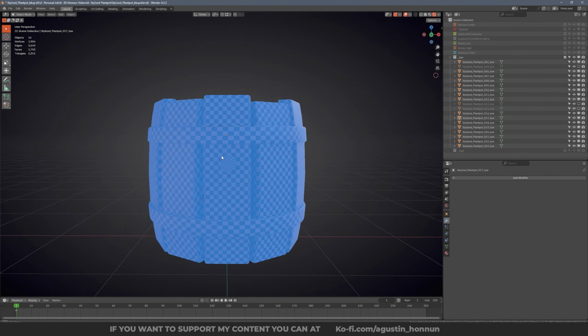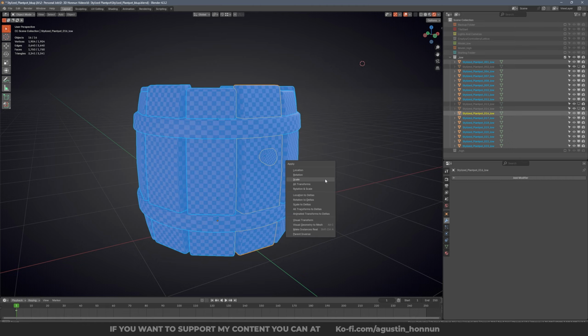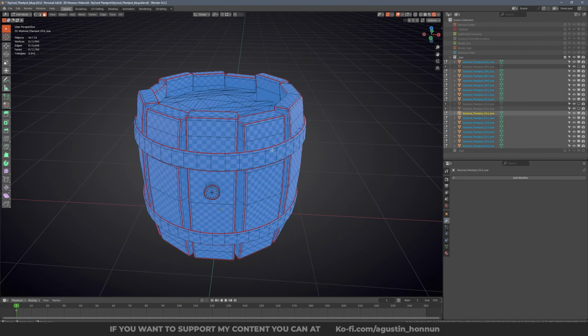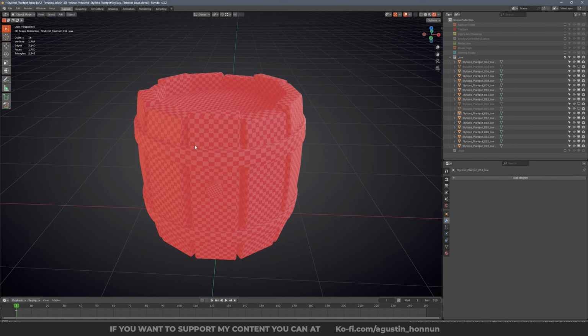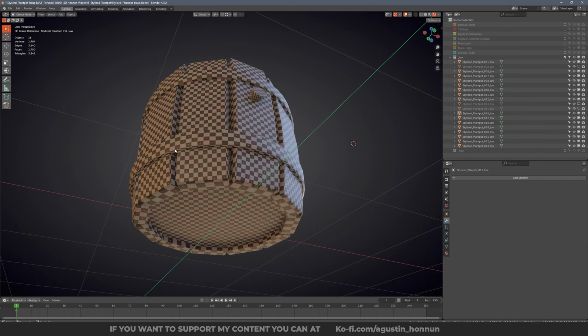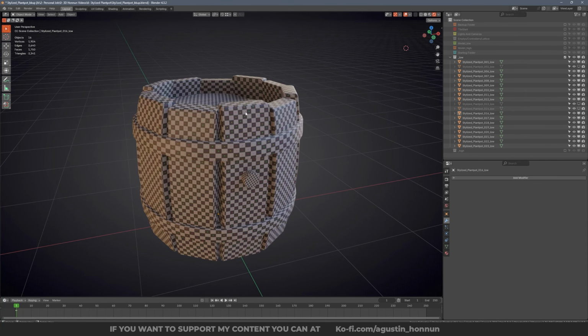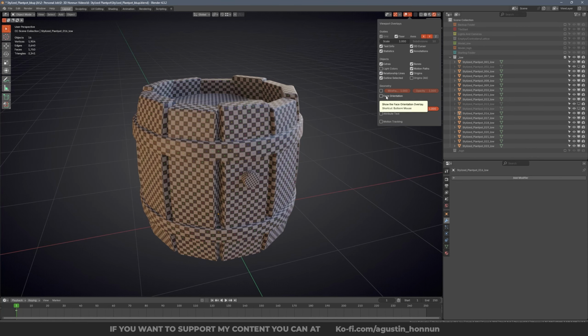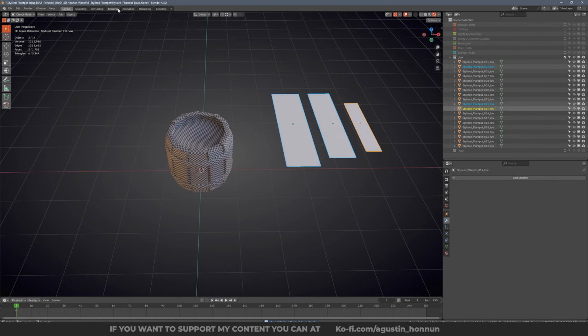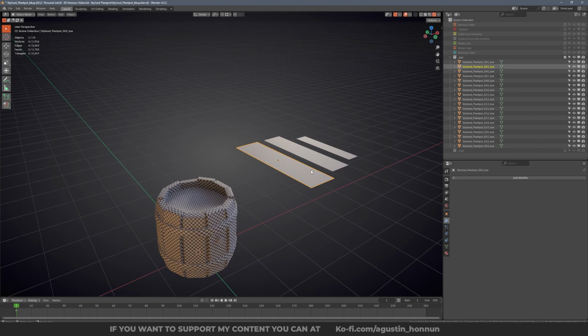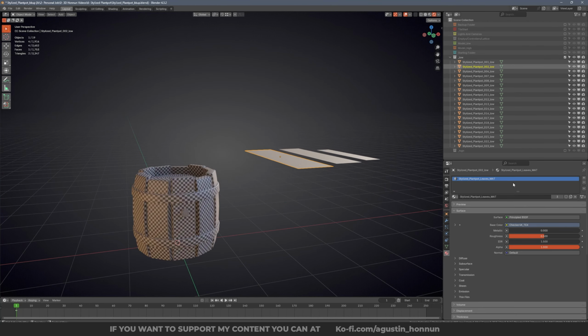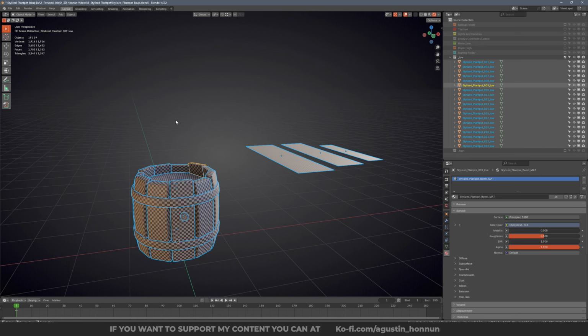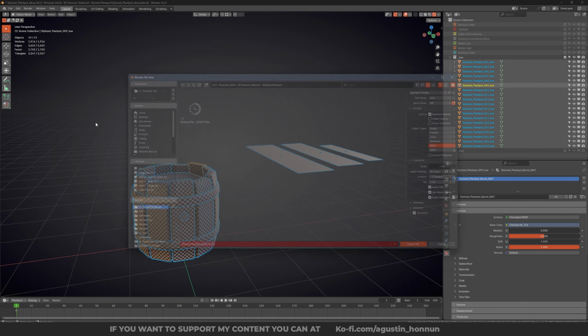Okay, make sure there are no red faces. If you apply scale and you see red faces, for example, like this, they are bad. You need to have all of them in blue. Remember to enable these, go here and face orientation. Okay, for the lips, I'm going to add also a checker. As you can see, everything now is correct. So we need to make sure we apply the materials and everything is good. And then we can export this. File, export FBX.